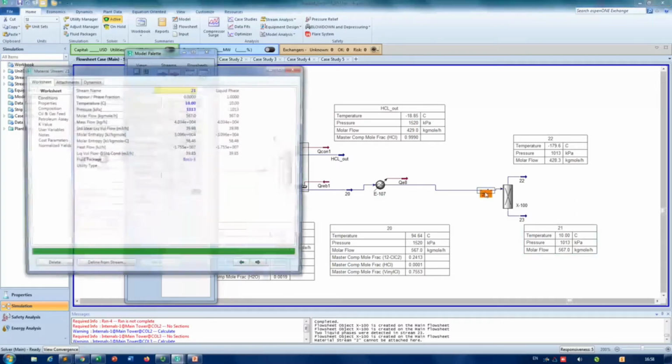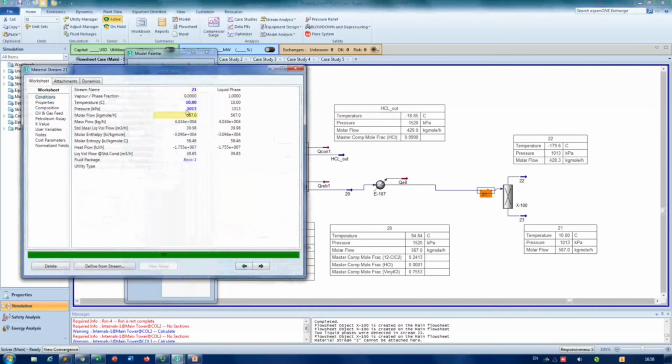So first I'm going to decrease the pressure. Let's put 5 atmospheres. You see there is a slight decrease in the temperature. So let us slightly increase the temperature. Go to 20. Okay, not bad. When I press 30 degrees centigrade, you see the condenser temperature is slightly increasing. So let's put 60. Okay, this is a perfect one. You see the condenser temperature is in the economical distillation zone, 33.52.